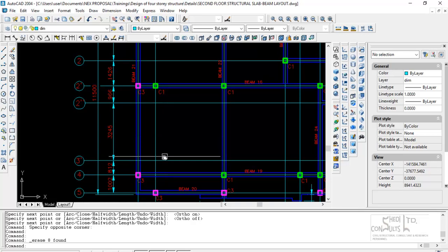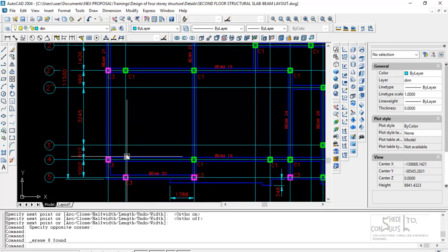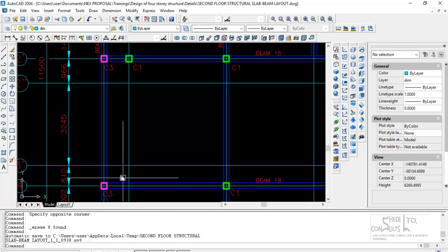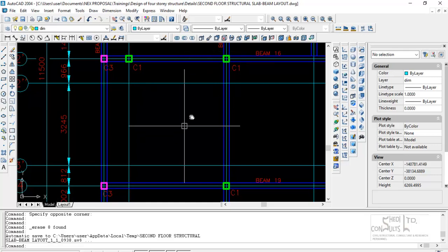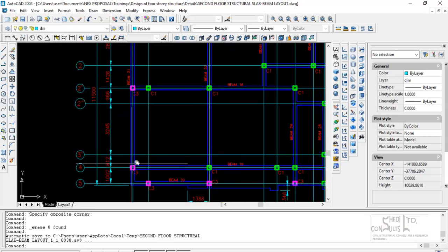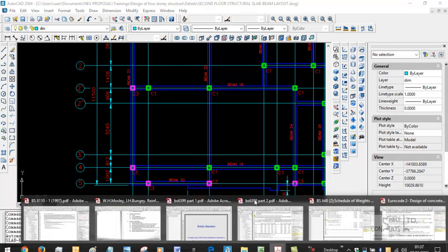So if the slab panel is continuous on 3 edges, one of the requirements of yield line construction is that yield lines form over the edges of boundaries, and they form over columns, and they intersect between boundary edges. These are some of the considerations of yield line. So if you look at the yield line formation of this slab, you will find that the loading from this slab onto this beam is such that you would have more load on the edges that are continuous. Let's look at these things clearly. Let's look at where the code specifies this.